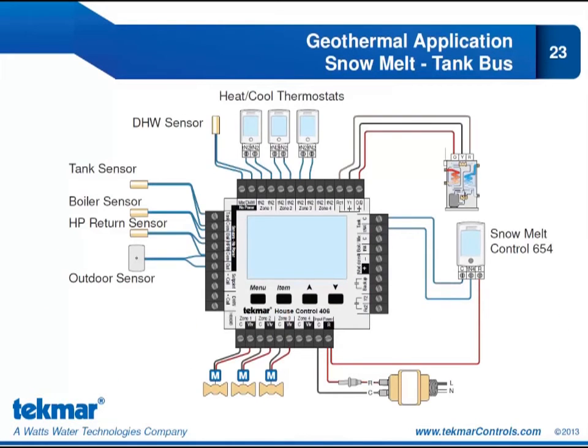So here's my electrical diagram to show you the wiring of the 406 with the other controls, the thermostats and the 654 for the application we just saw. So I have my 3 radiant zones, and we will control those zones by connecting heat-cool thermostats to each of the 3 zone inputs on the 406.